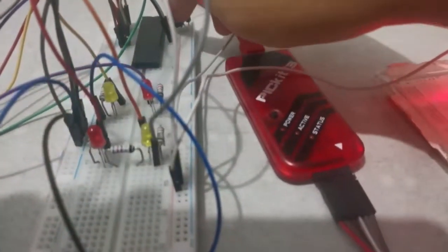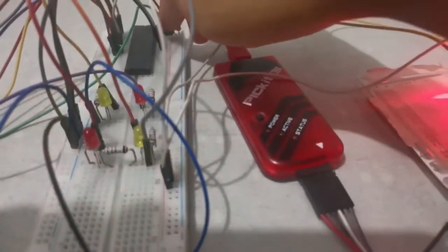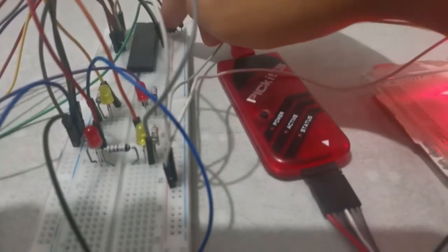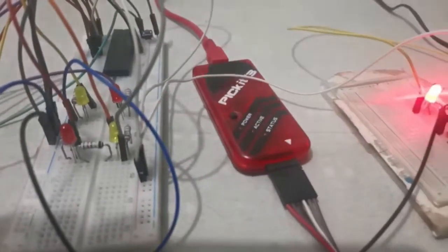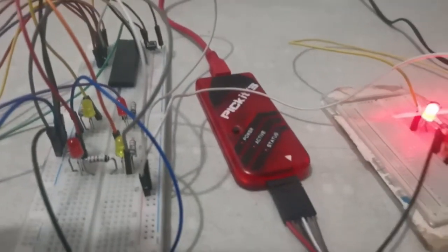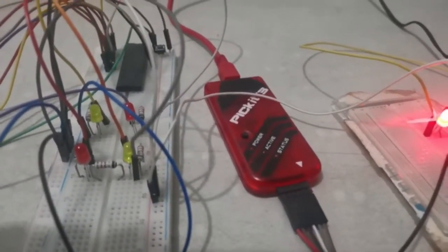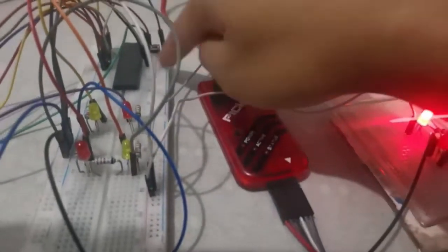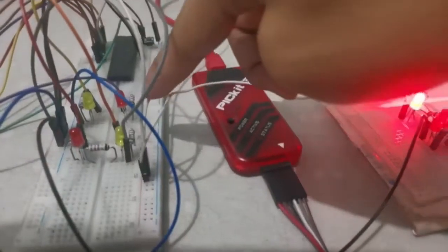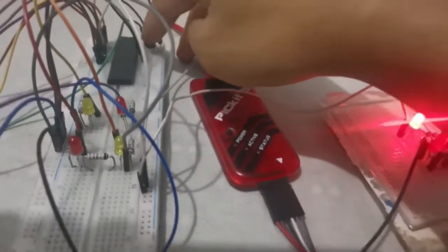That's because that's the only LED that is not connected to the ground. The reason for that is that when it is connected to the ground, the voltage across the diodes gets decreased, so they do not light up as much. So they are so dim when they're lit up. By sacrificing one LED, we can see that all the other LEDs light up.